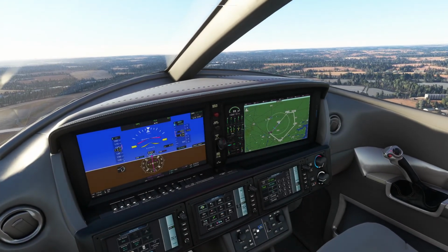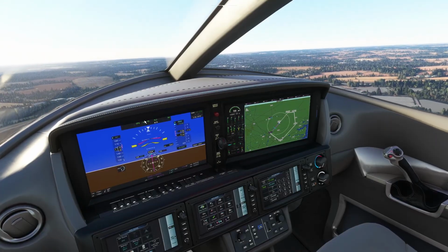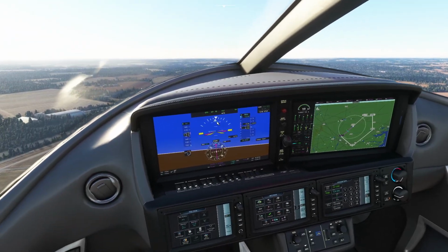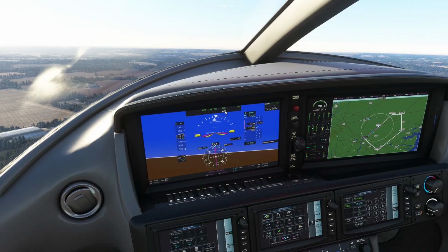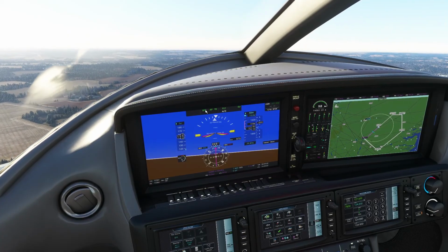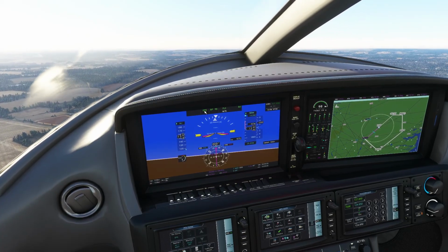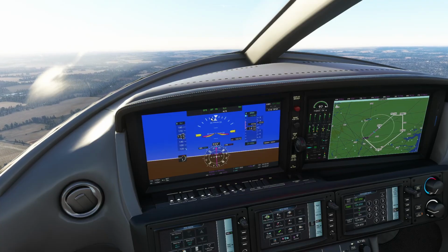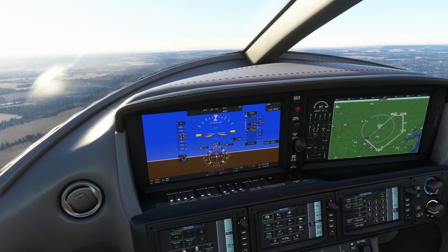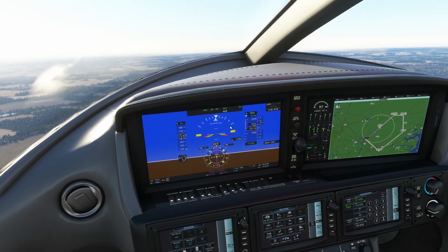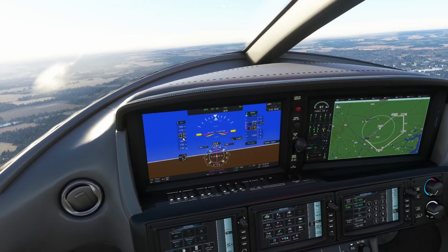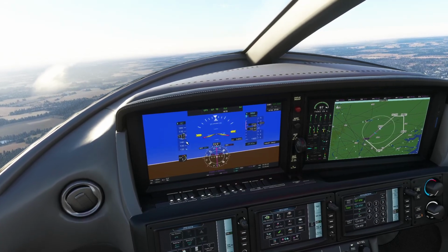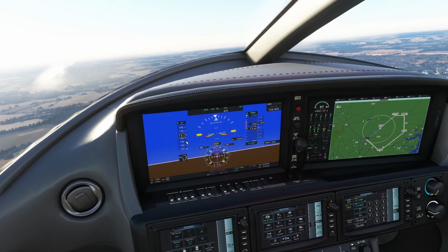And let's go for autopilot on, and you will notice, okay, so what has it actually done? It's going for the flight level change straight away, and it's holding GPS straight away, so we didn't have to intervene in any way. So it's climbing at, it's picked 150 knots seemingly to do the flight level change.